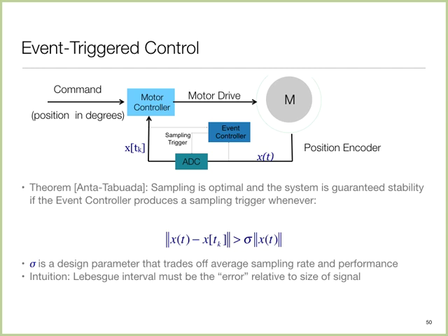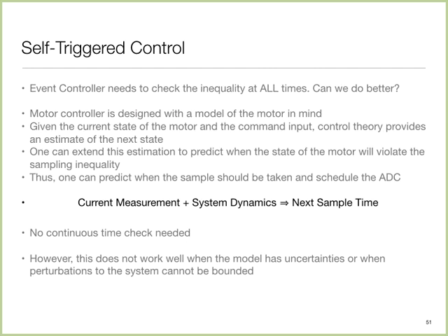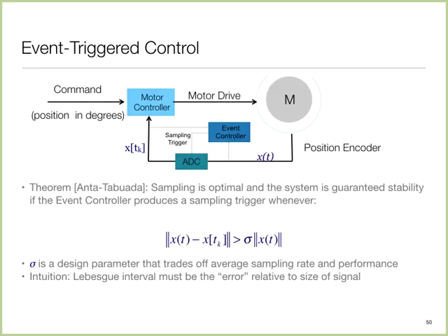So then there is an approximation of that. If it's below the threshold value that you're setting, you're multiplying the current value. If it has changed enough, then you are going to sample again. If not, then the A to D converter will not fire, but you are still monitoring this. So in this idealized thing, you are always monitoring on the analog side, and the moment the signal has changed enough, you are going to collect a sample. But you were saying it's better to have it on the digital side?